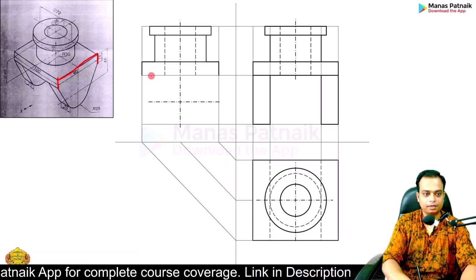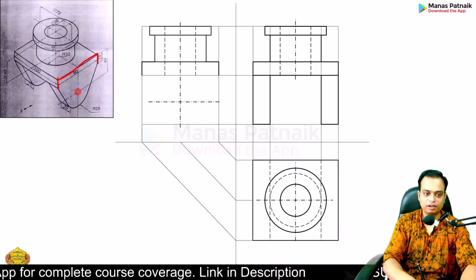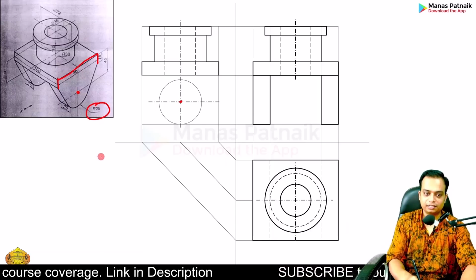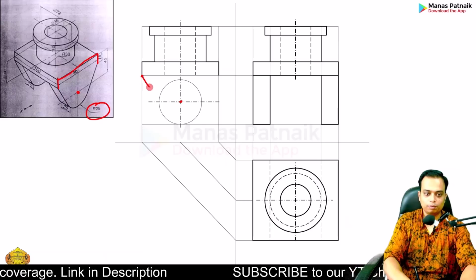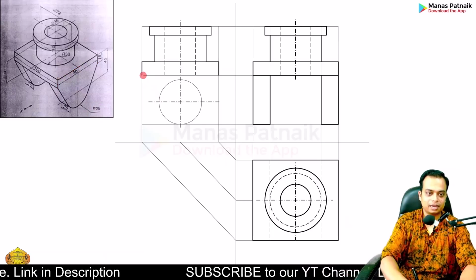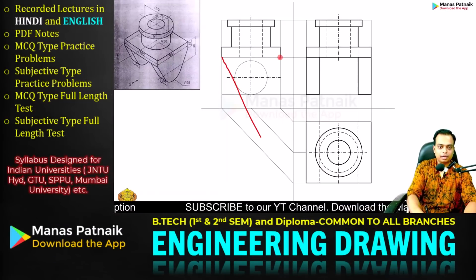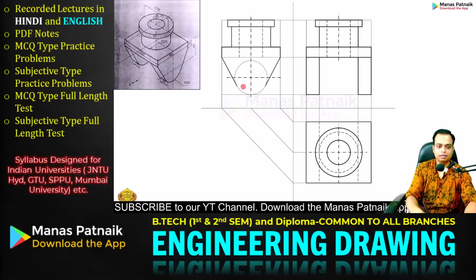So make it done. And now as far as the circular profile is concerned, using this as the center, make a circle of radius 25. Done, sir. And from these 2 points, don't make lines like this. Rather make lines in such a way that it becomes tangent, and from here also tangent. Okay, this way. And now darken this portion. Again, use a compass. Okay, so the diagram is done.